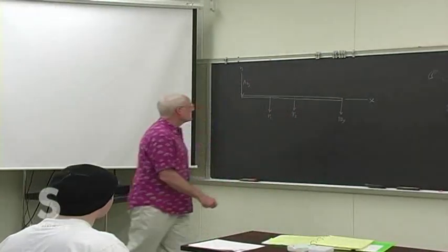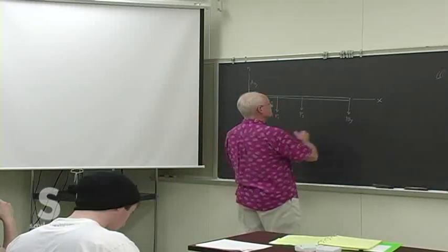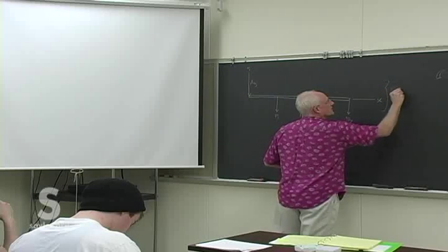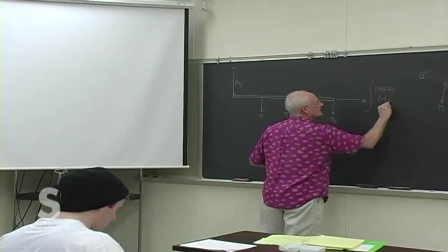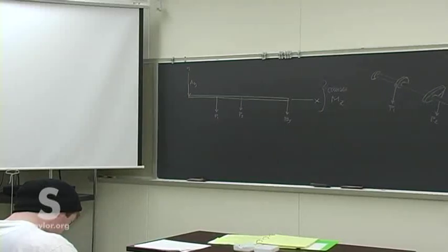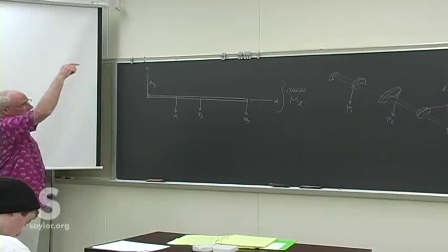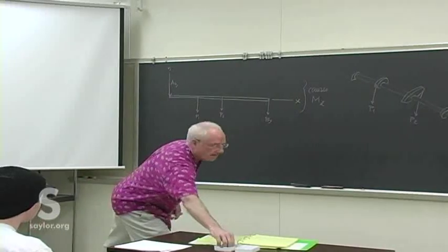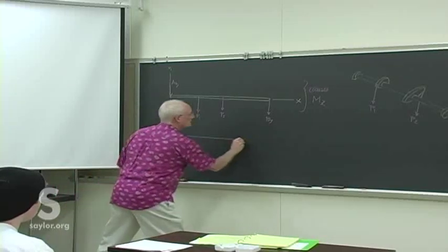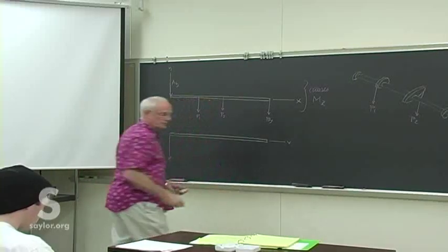But we can see that this looks very much like beams in transverse loadings that would cause certain moments. It would cause the beam to bend in some way, and would then cause some kind of moment with its direction defined by the Z direction using our right-hand rule. We could do the same thing, look down the Y-axis. So that'll give us the Z in that direction. X, remember, axially out like that.